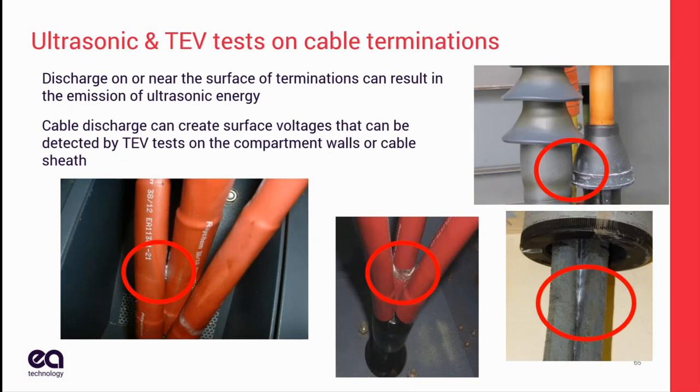We talked about surface discharge. You do have a lot of surface discharge in terminations. If you have unshielded cables or you have termination issues here, in the lower right appears to be unshielded cables. This white powder is PD. Here they have shielded cables, but above the shield is where they've got it too close together in a trifurcated cable. Same with the picture on the left.